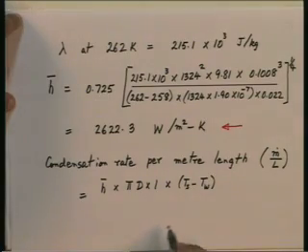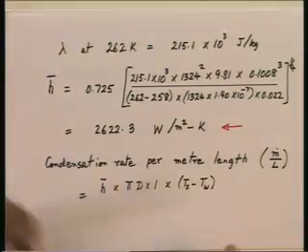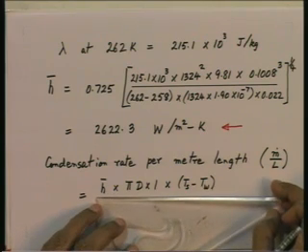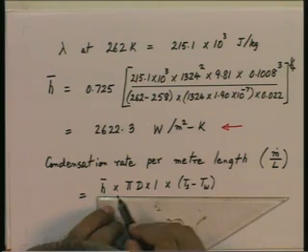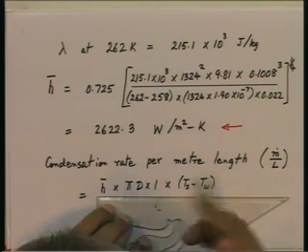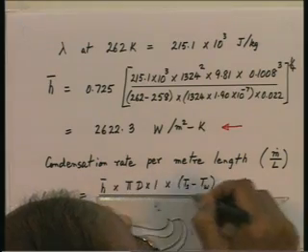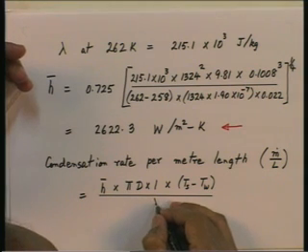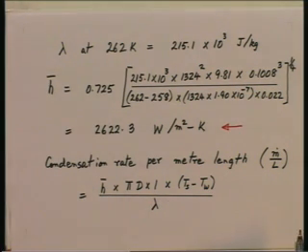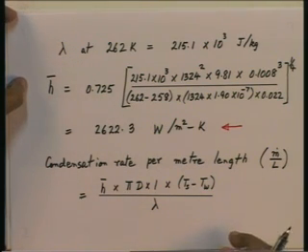This is not heat flux, sorry, it is the rate at which heat is flowing, Q. If you divide this by lambda, that is the latent heat, then we will get the condensation rate for 1 meter length, because we are taking 1 meter length, L equal to 1. So, now again substitute the numbers here.